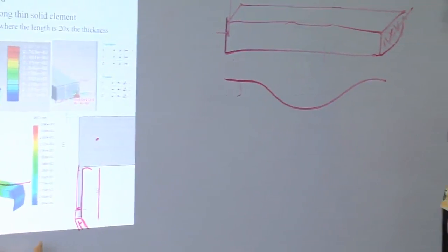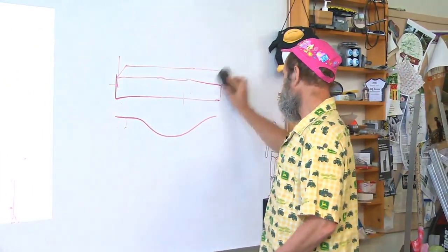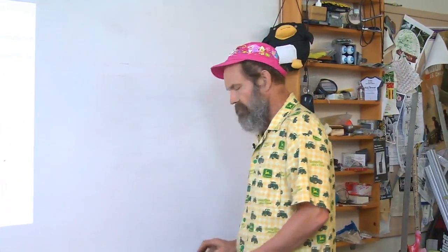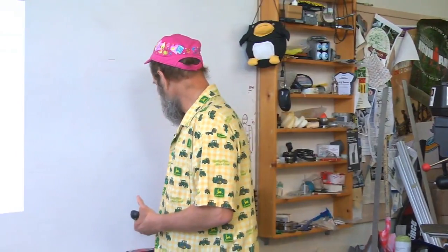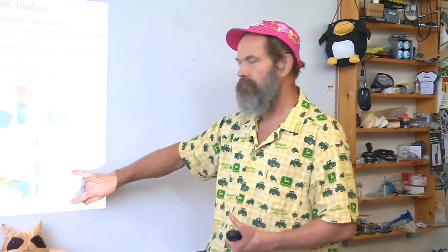This is also true for bolted joints, and we will be talking about this a lot more in the next topic, topic 9 on joints. There's a way you can model bolted joints very, very effectively in your solid model such that when you do the meshing for finite elements, you get a very accurate prediction of the stiffness of a bolted joint. So there are some tricks you can play when you're doing finite element analysis, where you're adding in compliance